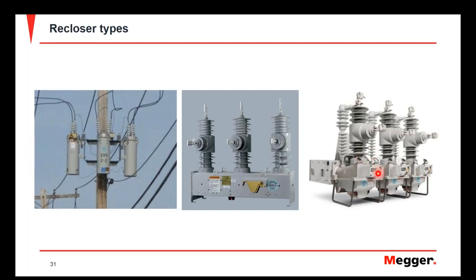Now, the last type that we'll talk about here is known as a single phase trip, 3-phase lockout. Excuse me, I'm sorry. This is 3 single reclosers. And there's 3 different ways that this recloser can operate. The first is a single phase trip and a 3-phase lockout, where each phase is going to operate independently for both protective and closing functions. However, if one phase moves to a lockout condition, then it's deemed as being a permanent fault, and all 3 phases are going to open and lock out.